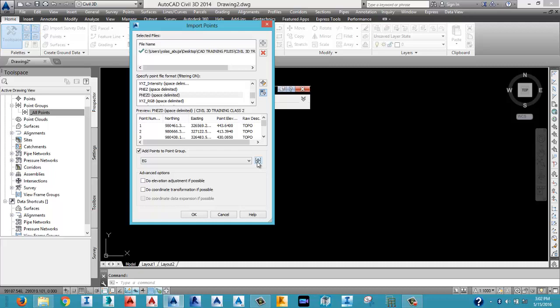Whenever a surveyor goes to site to pick information for us, they might be picking information based on the topographical nature of the area, or on the detailed features they find on the field. For example, you might go to site and find outcrops. You might pick the survey data of the outcrops, mark it out and then put it in a particular file.